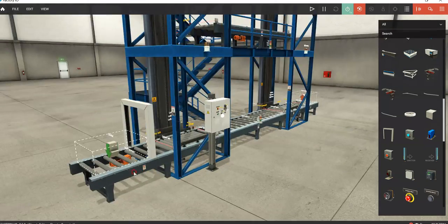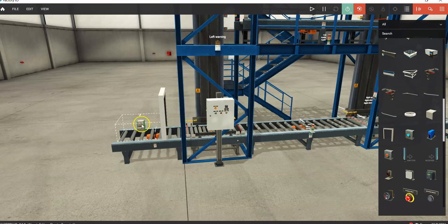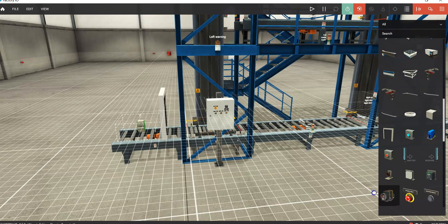So that's the bracket, and now we're going to put our visual sensor right on this edge, so we look at the color right as the pallet exits the emitter box, which is the dashed line. When you're looking at the sensors, you can hover over one, and the type of sensor appears in the lower left-hand corner. Here I'm hovering over an inductive sensor, now a retroreflective sensor, and then here is the vision sensor. So we're going to grab it and try to put it on our bracket.